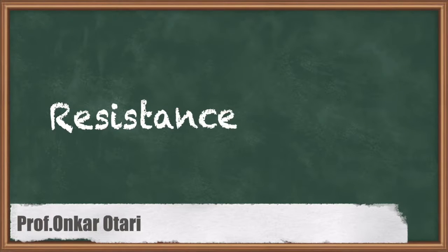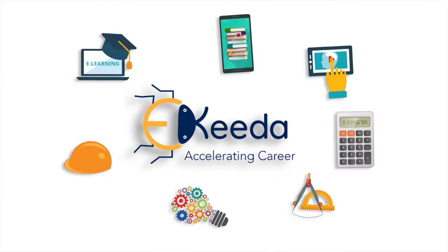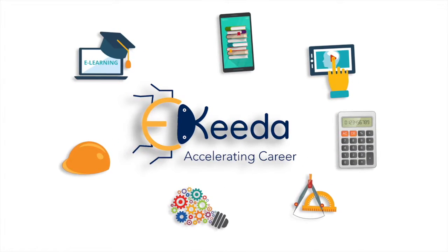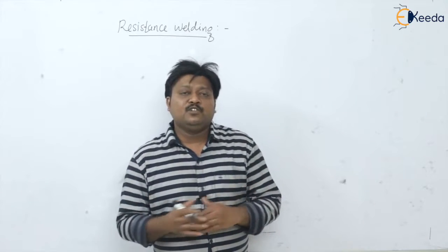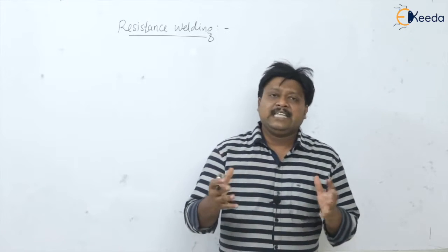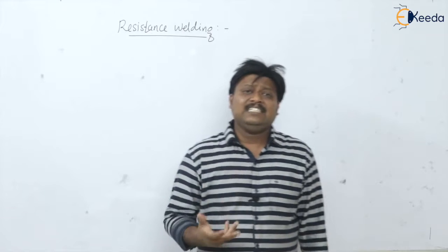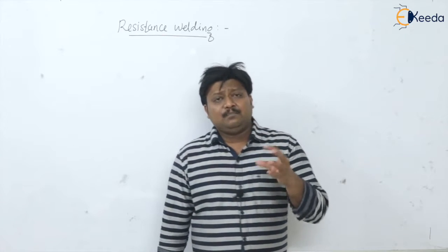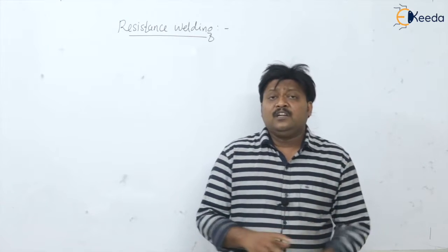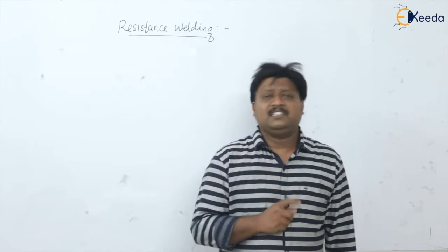Dear students, in this video we are going to start with resistance welding. So far we have seen the fusion welding processes where heat is applied into the joint, but in contrast to that, in resistance welding, the heat and pressure both are used without any use of filler rod or fluxes.